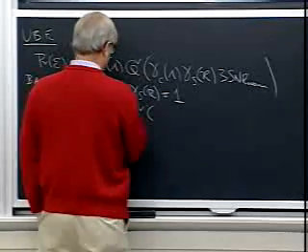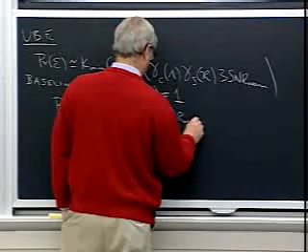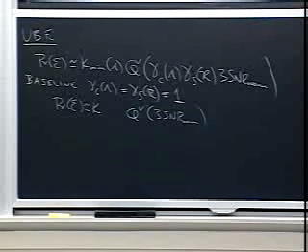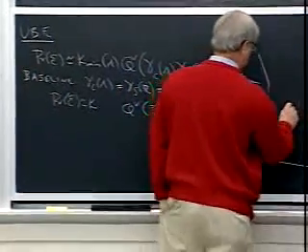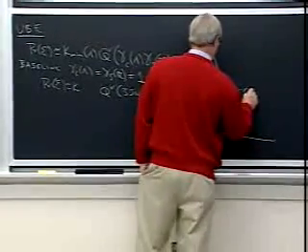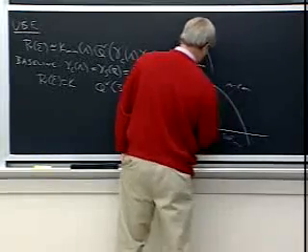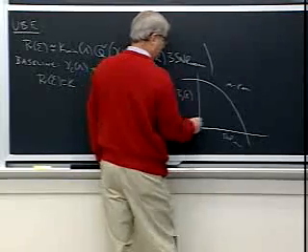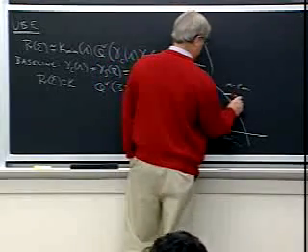Q hat, but it does give you the right coefficient out here too, depending on whether you normalize it per 2 dimensions or what. It just gives you Q to the square root of 3 SNR norm, which I hope you remember from chapter 5. So this was our baseline curve for MPAM or M by M QAM. We just plotted versus SNR norm the probability of error per 2 dimensions, which is what I recommended, and we got some curve. All right, so this is the baseline.